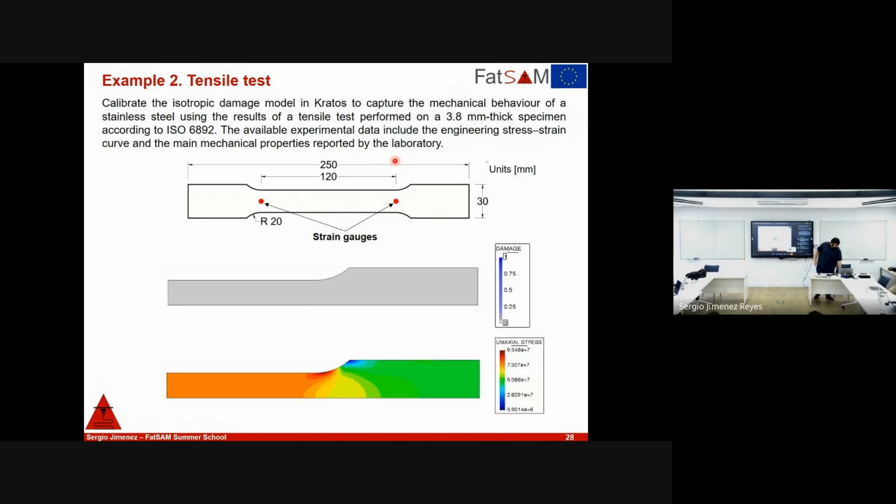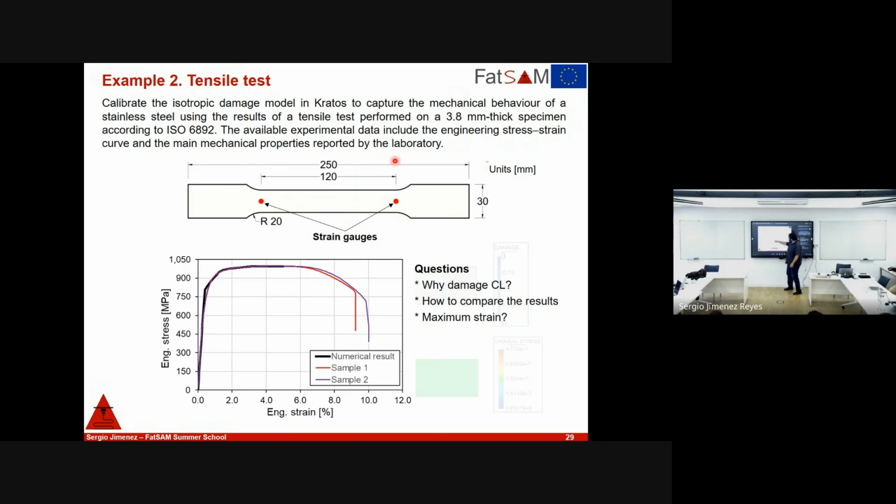In my case, I arrived at 4%, if I'm not wrong. This was the calibration that I obtained for this material. Then what happens in the high cycle fatigue regime? In high cycle fatigue, we stay here, below the yield. And in low cycle fatigue, we usually stay below the ultimate strength, and indeed below this region here. So we are really at 1 to 2% maximum, which is 0.01. So you can stay there.